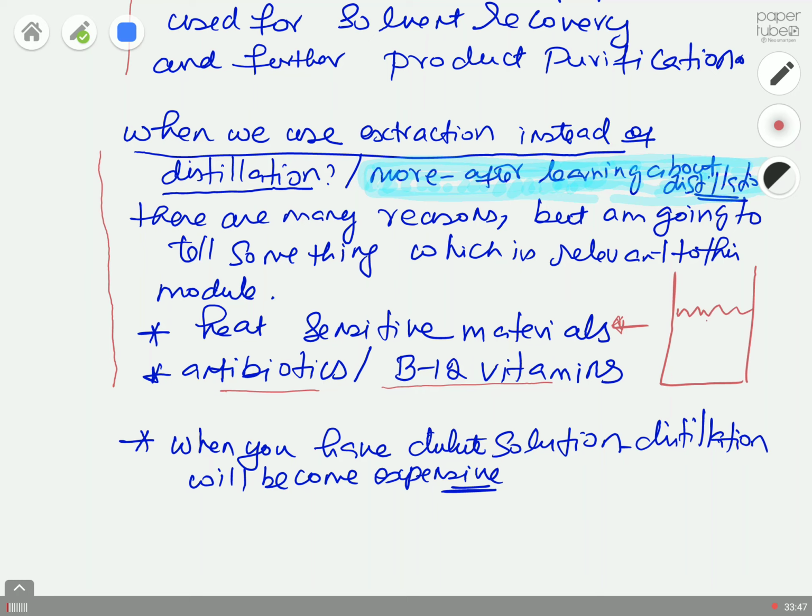So imagine you have a very large volume of some solution with some solute particles, and you have a tiny bit of your solvent. If this solvent can take the solute particles from the solution, and concentrate them, then after equilibrium you can take this tiny bit of solvent and evaporate it, and then you get your product. This way you spend less energy. So that's the meaning of this.